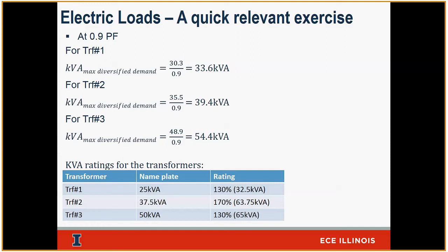Yeah? If you can consistently go that much above nameplate rating, what is the nameplate rating? It just tells you the threshold of where you optimally need to be. Now, if you push it to 130% on top of the nameplate, you're still within okay boundaries without really killing the transformer or causing damage to the transformer.